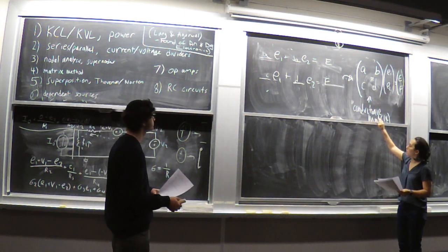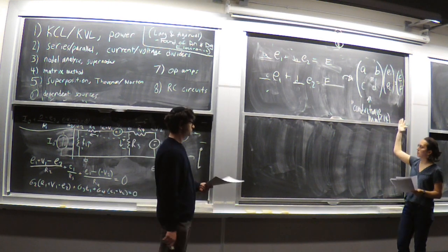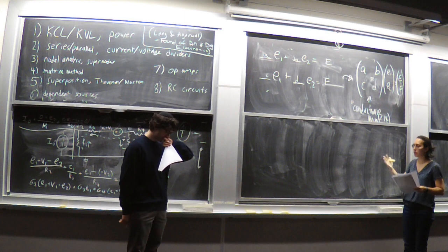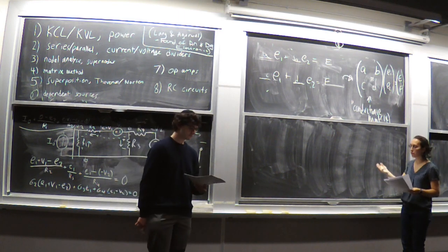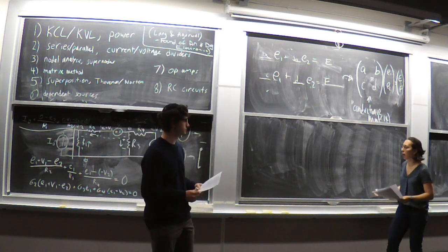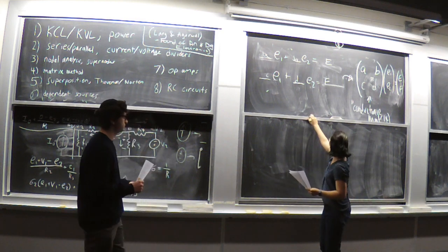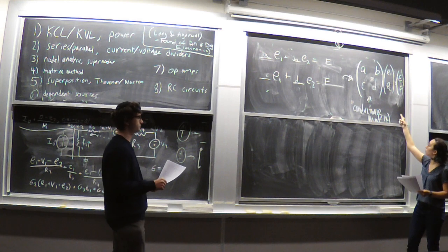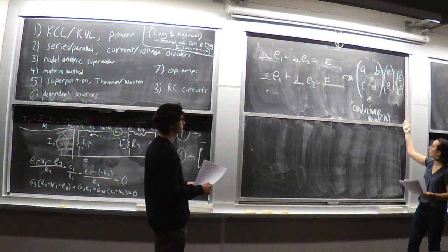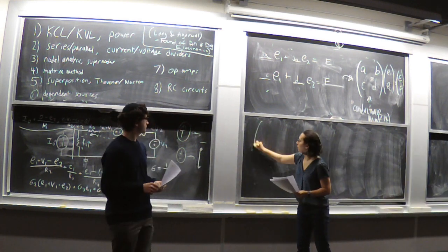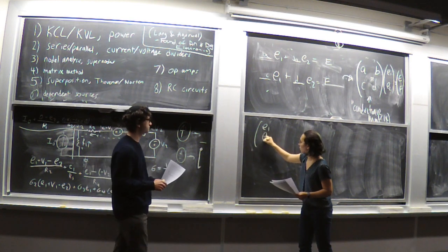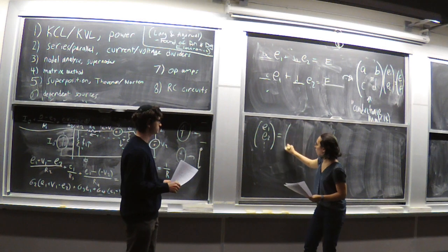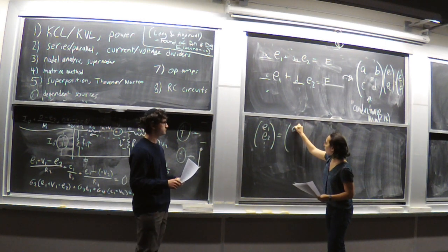Okay, so as I was saying, this algebra that we just did shows us our circuit is linear, and this happens when the elements in your circuit are linear. So V equals IR, that's linear. The second thing we learned from this is if we were to solve this equation, we would get E1, E2, and so on, and we would have some constants in front of it.